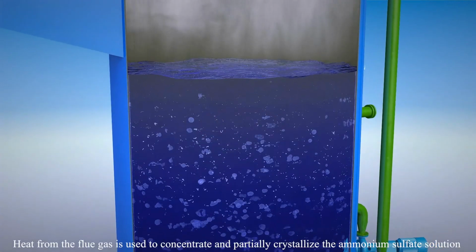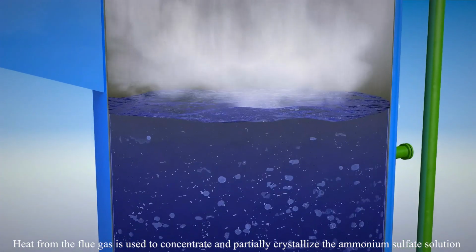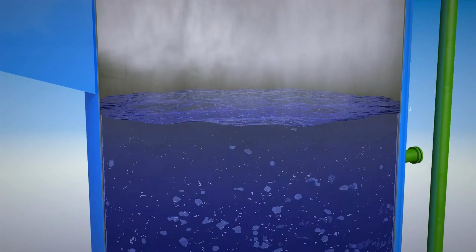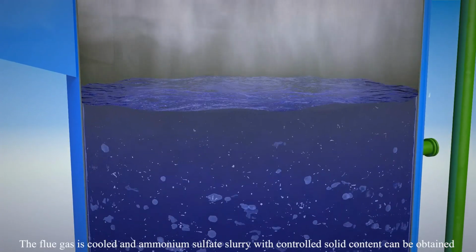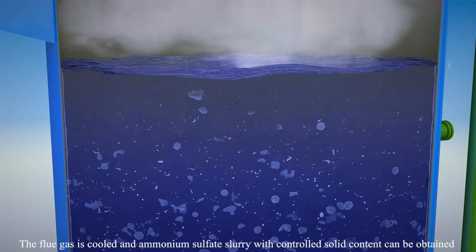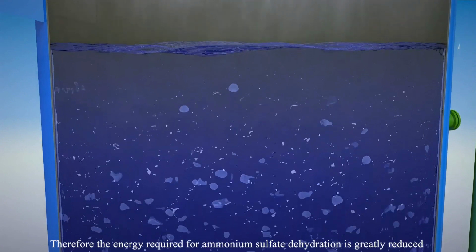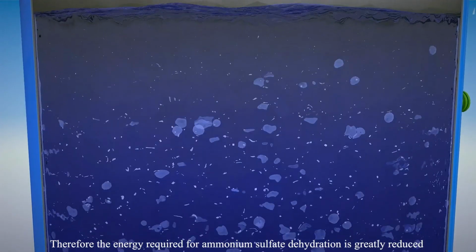Heat from the flue gas is used to concentrate and partially crystallize the ammonium sulfate solution. The flue gas is cooled and ammonium sulfate slurry with controlled solid content can be obtained. Therefore, the energy required for ammonium sulfate dehydration is greatly reduced.